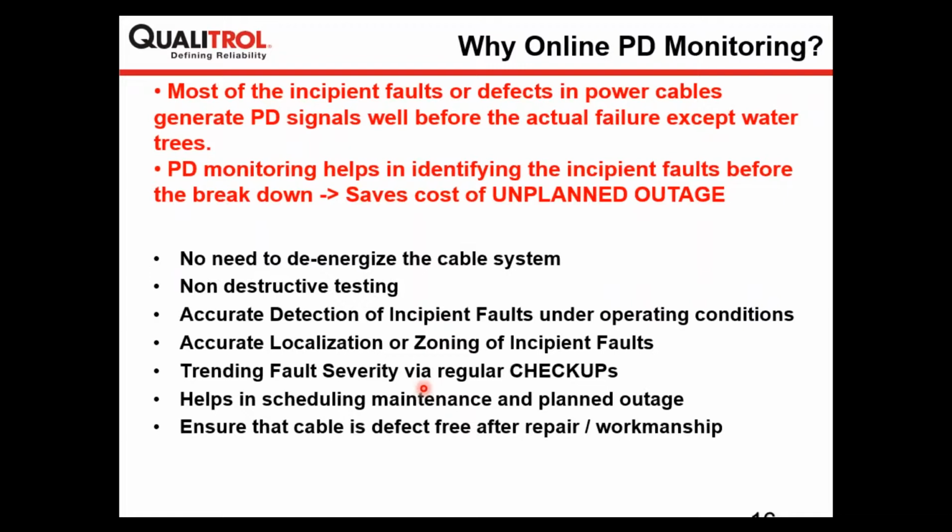And when you do online partial discharge measurement, there is no need to de-energize the cable system. It is a non-destructive testing. We will not be overstressing the power cable. We will not be applying any external voltage. The cable will be operating under normal conditions. And if we apply the technology in the correct way, by which I mean if we know the cable grounding scheme, then we can accurately detect and locate, or in the second case zone, partial discharge along the length of the power cable.